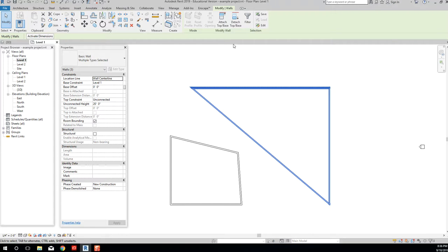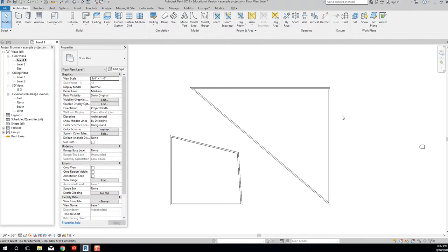Which is kind of a no-no in AutoCAD, right? If you're in 2D AutoCAD, because if you hold Shift down and you move your cursor in AutoCAD, you pop into 3D. And if you continue to draw 2D lines in 3D, you get crooked lines, right? So when you're going back and forth between AutoCAD and Revit, you just have to be careful about how you're navigating. To deselect, I'm going to hit escape, okay?